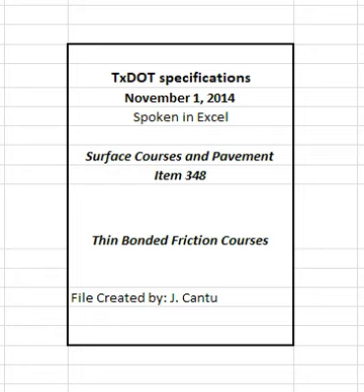4.9.6 Recovered Asphalt Dynamic Shear Rheometer, DSR. The engineer may take production samples or cores from suspect areas of the project to determine recovered asphalt properties. Asphalt binders with an aging ratio greater than 3.5 do not meet the requirements for recovered asphalt properties and may be deemed defective when tested and evaluated by the Construction Division.